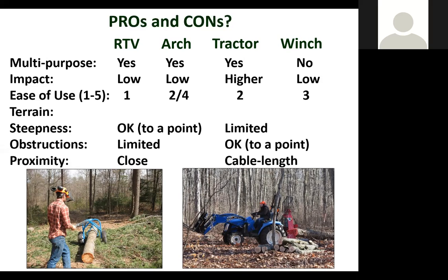We have at times combined the tractor 3-point hitch mounted winch with the arch to pull a really big piece of wood. I wish I had a video of this, but I don't. We've chained the arch to a tree that was hung up, and moved off at some distance, and put a cable on the tongue of the arch, and used the arch to pull down a tree that was hung up, and not have to be anywhere near it when we drag it out of a tree.